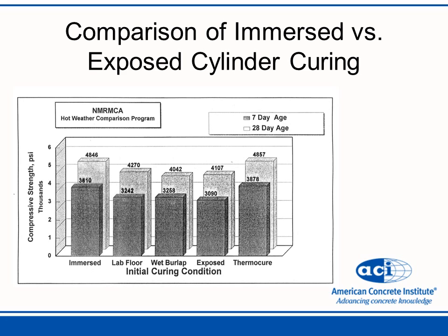And as you can see here, the cylinders that were exposed, left out in the sunlight like we do normally on job sites, had the lowest 7-day breaks, or 7-day cylinders, and then they were about 750 psi lower than the thermal tube carrying box, and also a lot lower than the cylinders that were immersed in water.